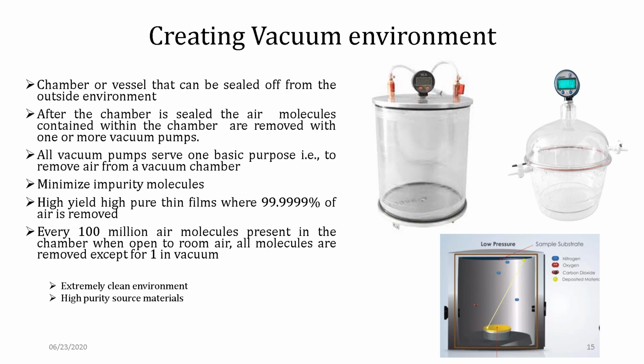These are typical vacuum systems, right from a desiccator like this to a very hi-fi chamber like this. What we actually do is reduce the number of air particles inside such a chamber by sucking out the air. And the kind of vacuum that we are dealing with depends on the type of pump that we use.